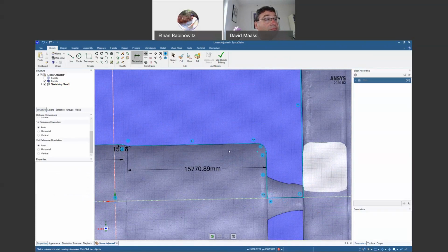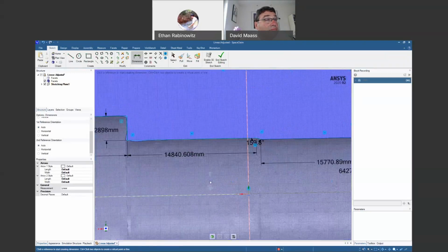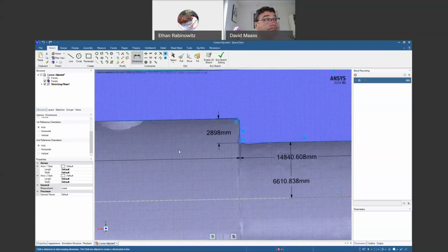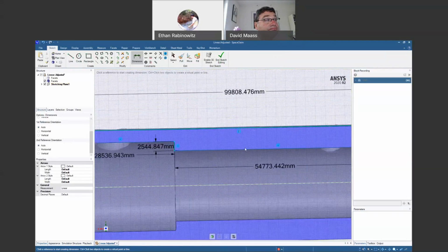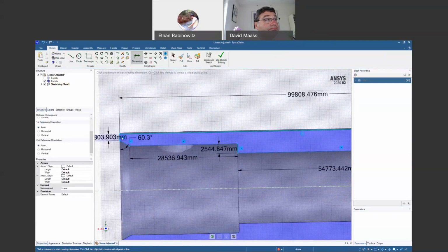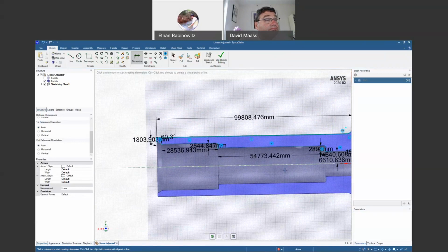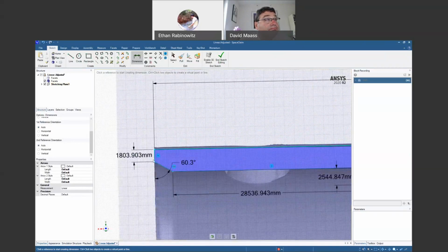And then when I dimension different diameters, I could just go right down to this datum axis there and use that as my reference. So we'll see here that a number of these I can set up and constrain further by going down there. This one is constrained and this one is constrained because, oh no, you know what?